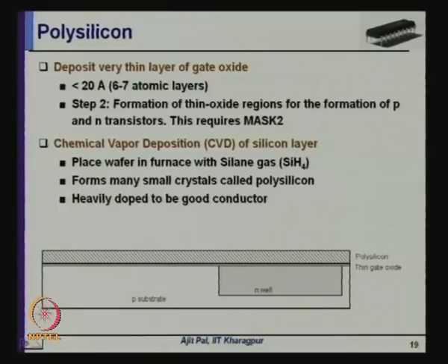Then on top of that you will deposit a polysilicon layer, using a technique known as chemical vapor deposition or CVD, on top of this silicon dioxide layer.